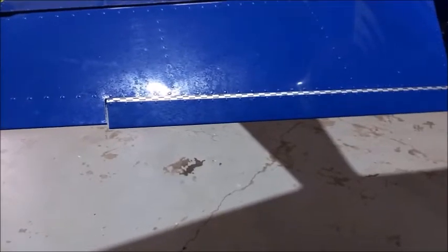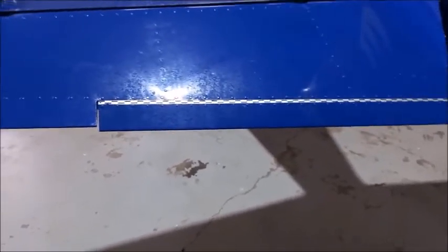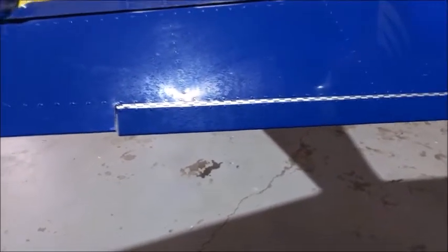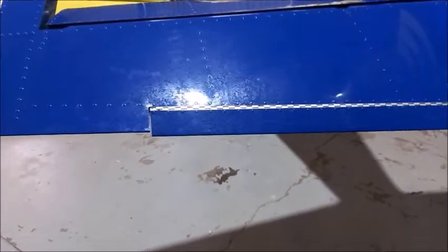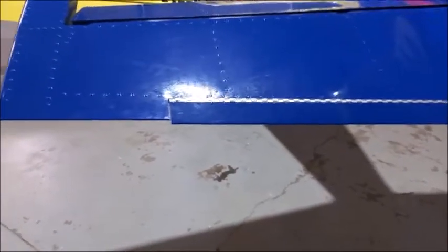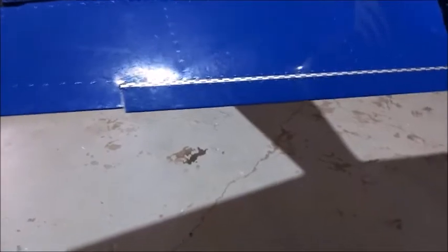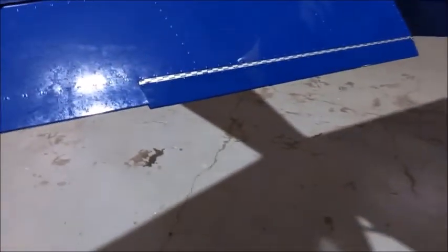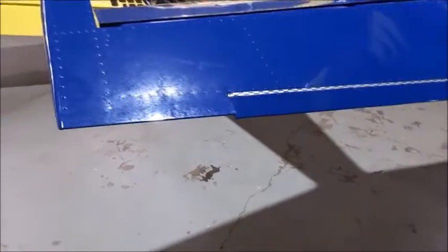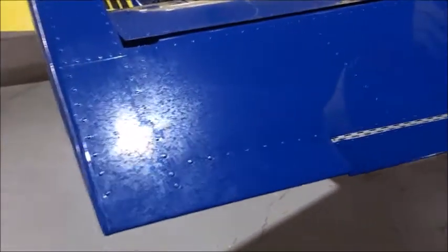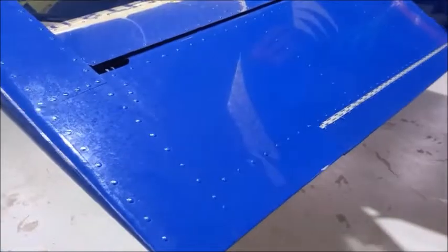So if you find that the aircraft is pitching up a bit too high or a bit too low, and you're ascending or descending while the aircraft is supposed to continue straight and level, you're able to adjust this, and this little control surface is able to correct that adjustment and helps you to fly the aircraft with less pressure on the control stick.